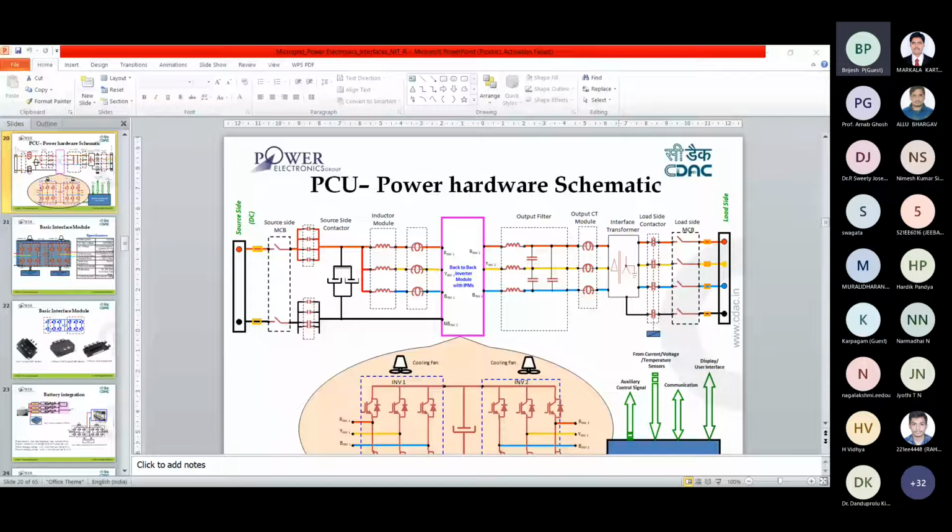We can have 12 PWMs from each DSP, so it is not sufficient for running the complete three legs. We need about 36 PWMs. Then we went for an FPGA core processor also.